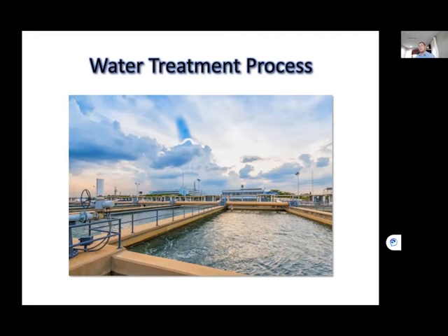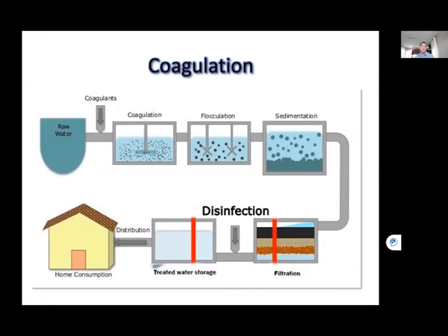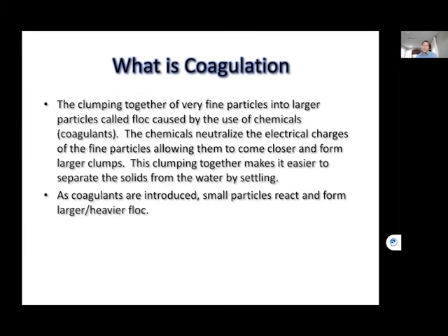Moving on to the water treatment process. So we've got our reservoirs, we have to manage those reservoirs, and now we have to treat the water. The first step in the treatment process is coagulation. What is coagulation? The clumping together of very fine particles into larger particles called floc, caused by the use of